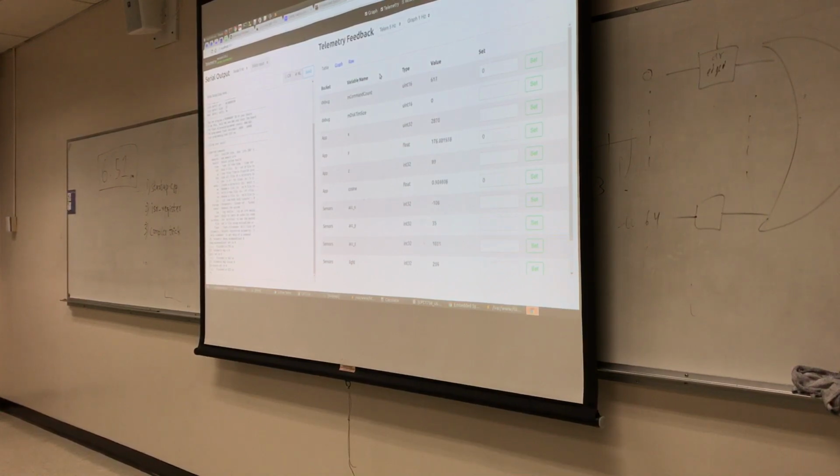Another thing is if you have things printing out willy-nilly that aren't inside of a command for telemetry, it will try its best to filter out that stuff and filter out the message it sends, but it's not always perfect, and you'll end up getting a lot of garbage popping up on your screen. So if you're doing a printf all the time, telemetry will not function fully.